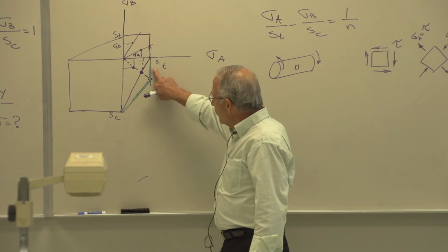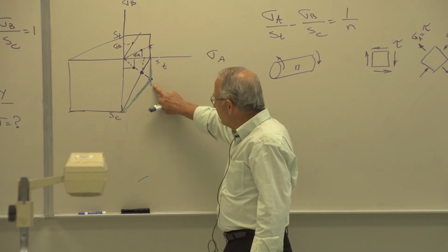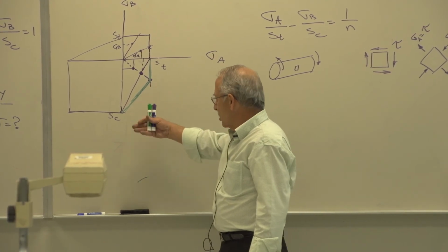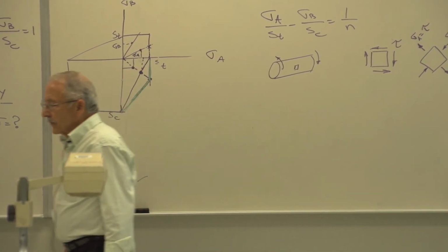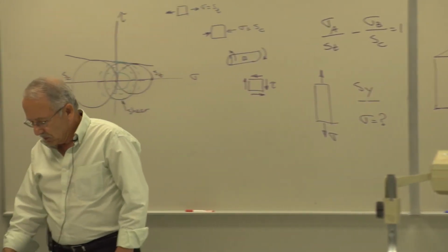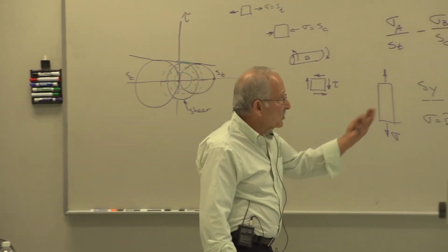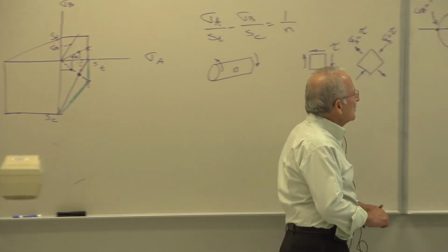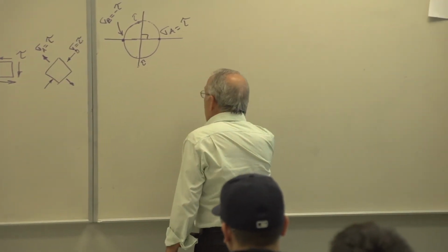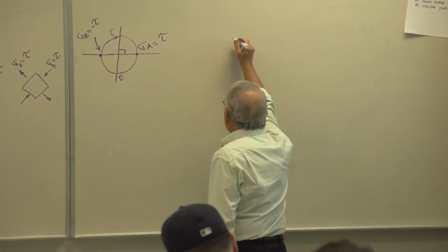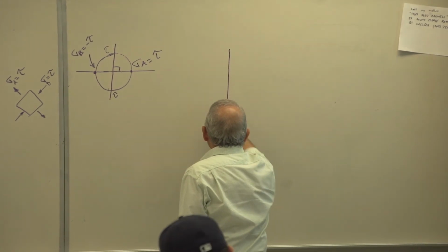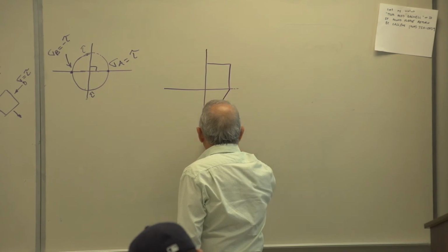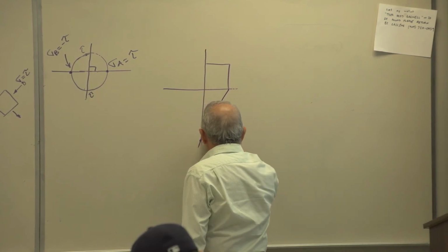The equation for this line is just ST over sigma A. For that one is a little bit longer and drawn out. It's in your book, so I won't rewrite it on the board. And I'm not a great fan of equations in general. You should actually understand what you're doing rather than plugging numbers into equations. But let me just show you, they have an equation in the book where they find the factor of safety not for the modified Mohr, but for the Coulomb-Mohr, for this one. And just show you quickly how that's done.